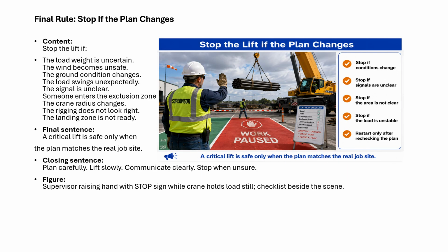Final rules. Stop if the plan changes. Stop the lift if the load weight is uncertain, the wind becomes unsafe, the ground conditions change, the load swings unexpectedly, the signal is unclear, someone enters the exclusion zone, the crane radius changes, the rigging does not look right, or the landing zone is not ready.